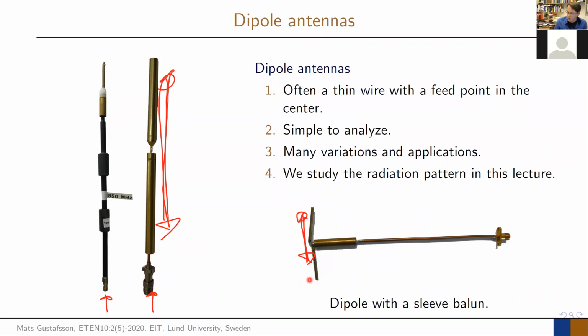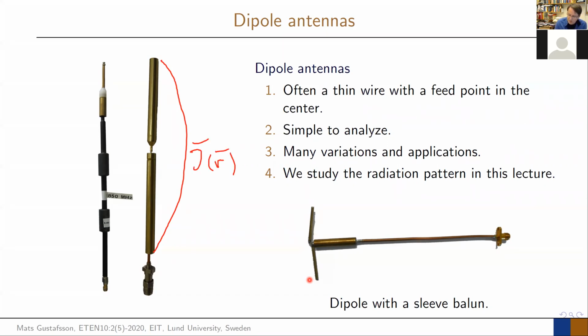This week, we'll only do one thing, and that is what we say here: you have typically a current density, and in one approximation, the amplitude looks like a cosine or sine function. So the current density that you have here as a function of the position on the dipole is strongest close to the center. Here is the opening of it, and it's 0 out at the edges. Here the current approaches 0. And that means it's the same thing that sits on this one.